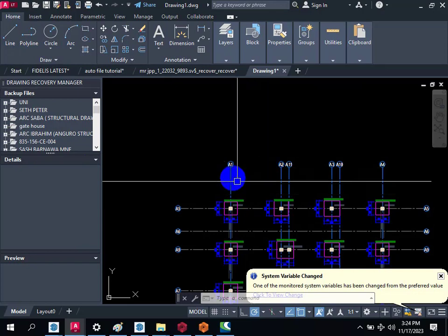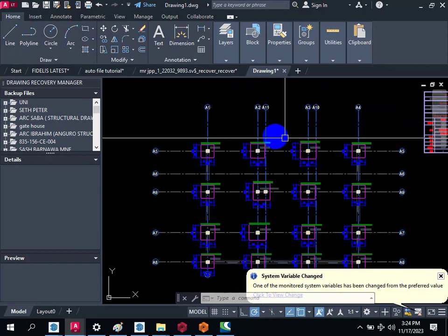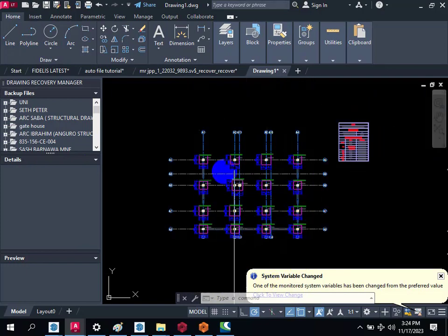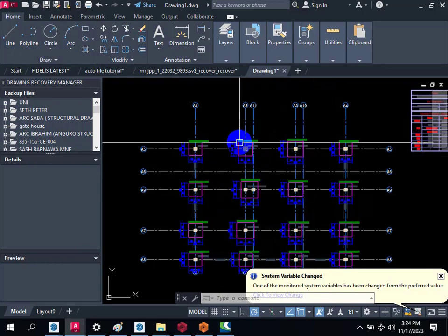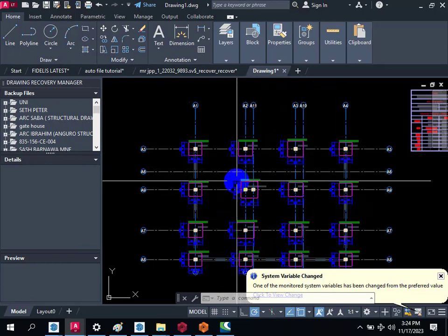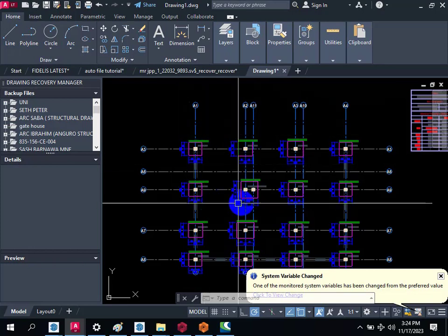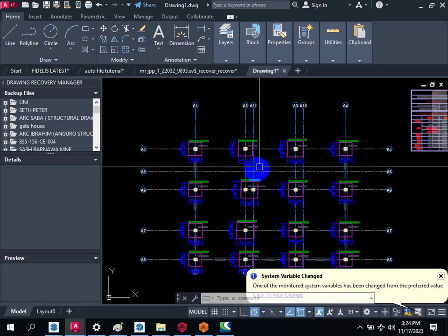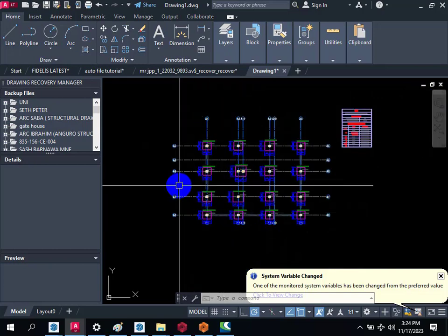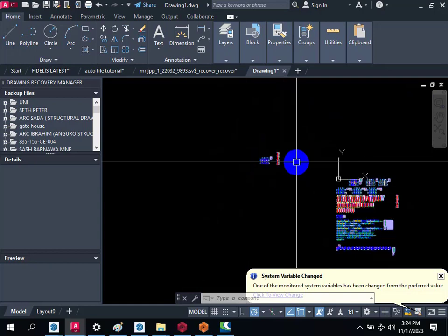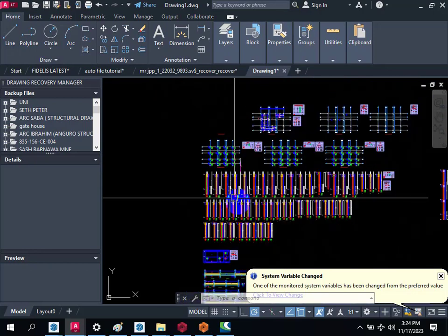In that case, you are having different types of column. But in this case, we are going to have almost the same type of column, because even when the software analyzes and does the design, you will see that everything is approximately the same: the reinforcement, the links. So you can adopt just one type of column, and there will be no need of printing all these columns.